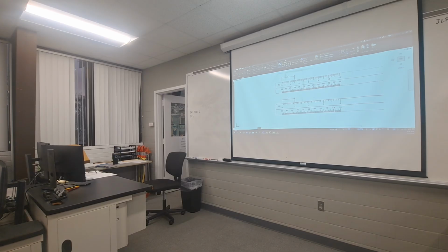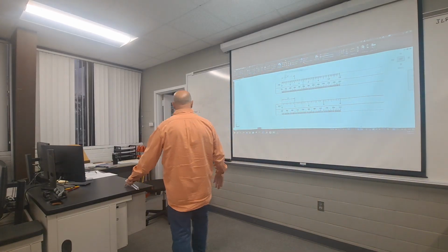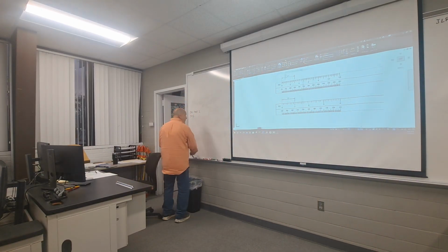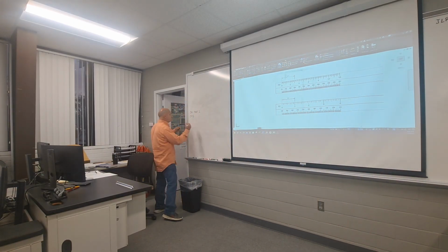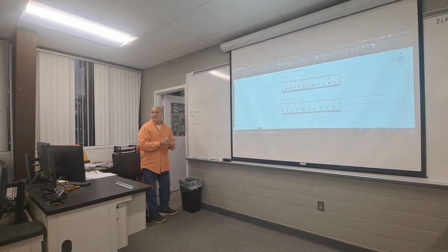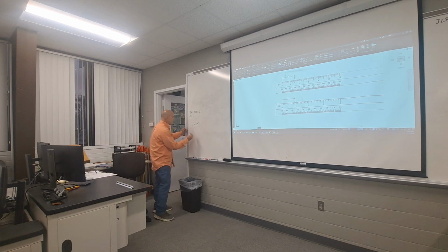All of your scales begin with 1 inch equals a number of feet. Whenever you put it in your title block, if your scale is 1 inch equals 10 feet, we don't put this dash 0 inches on that. That top one up there that we're gonna reference in a minute is 1 inch equals 30 feet.